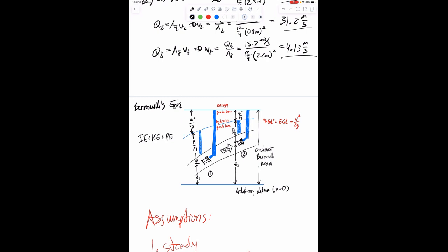You see there's two pipes. One of the pipes is kind of chilling at the edge of the tube. The pipe chilling at the edge of the tube cannot record any kinetic energy. It can only record internal energy and potential energy. That's the hydraulic grade line. It cannot record the velocity. But the tube that's stationed right in front of the moving fluid, you can then record the kinetic energy for that section. And that's the tube that gets you to the energy grade line. Otherwise, when you don't put your tube there, you only get the hydraulic grade line.